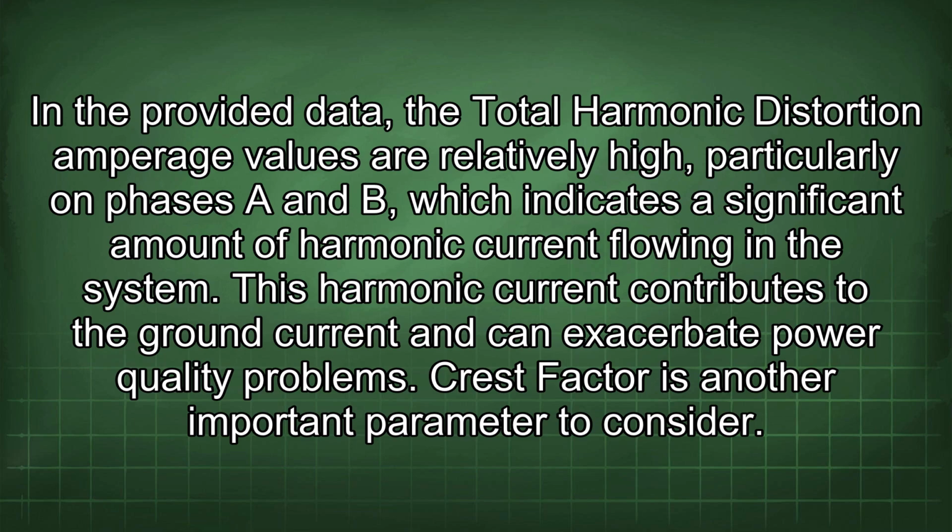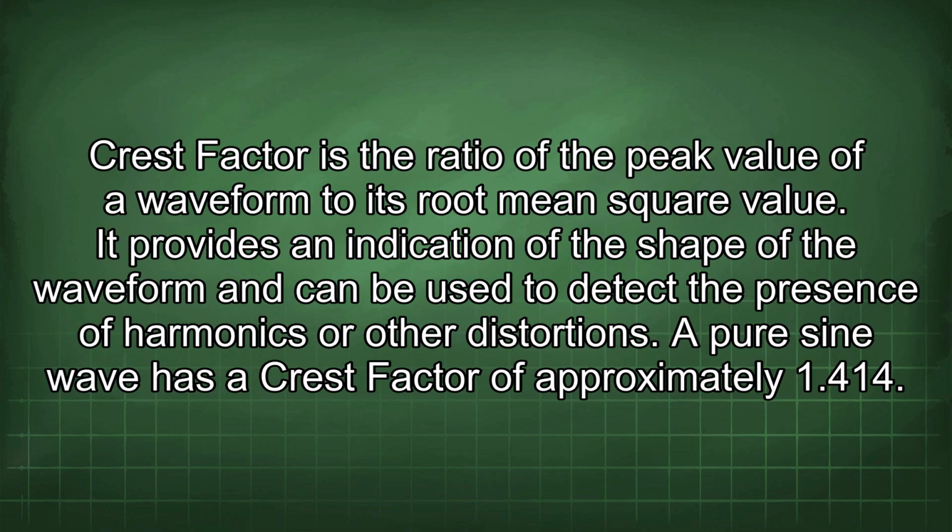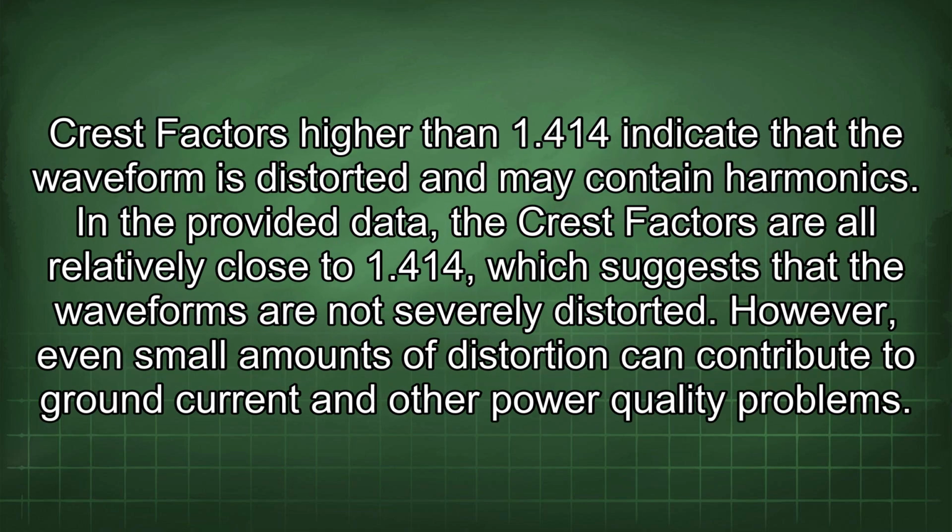Crest factor is another important parameter to consider. Crest factor is the ratio of the peak value of a waveform to its root mean square value. It provides an indication of the shape of the waveform and can be used to detect the presence of harmonics or other distortions. A pure sine wave has a crest factor of approximately 1.414. Crest factors higher than 1.414 indicate that the waveform is distorted and may contain harmonics.